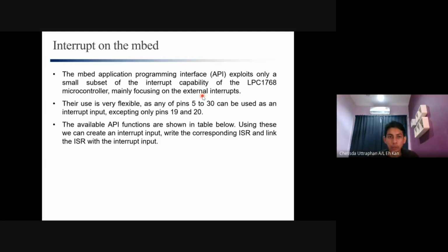So to do that, you need to control the register inside the microcontroller that controls the ADC. You need to turn that on and set the speed of the ADC. One thing is that inside that register there is one bit we call the interrupt flag. That flag will tell the microcontroller when the conversion is finished.